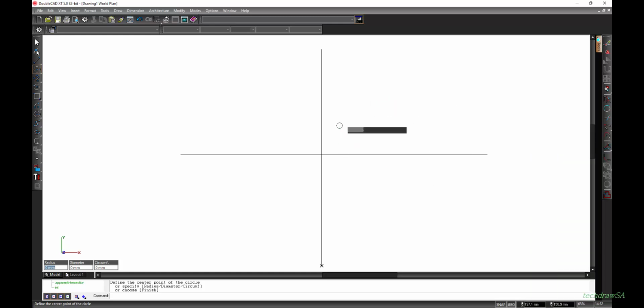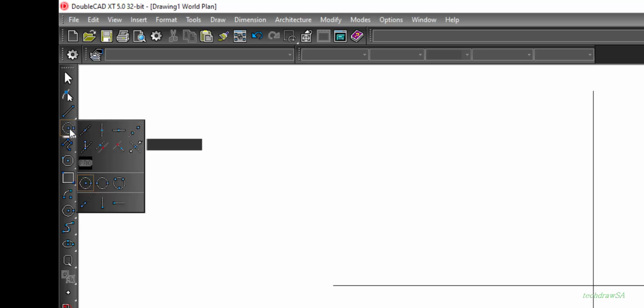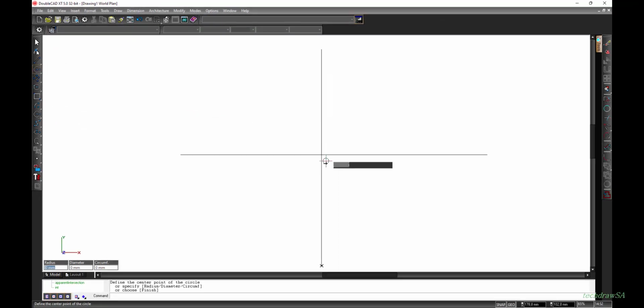Now when we want to draw on our canvas and I want to draw in the margin lines to space the beginning of each of the different views properly, I'm going to go to the construction circles tool, and I'm going to make sure that I've got the circle construction selected. With that selected, you must be very careful that you don't just click anywhere and snap, because it might be that there is a snap reference point that you are not aware of that it snaps to.